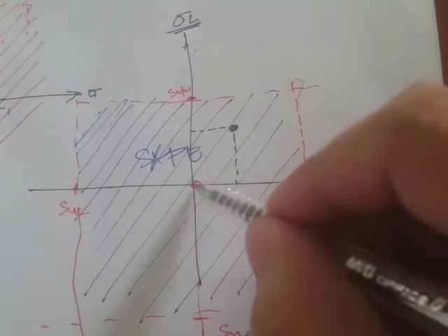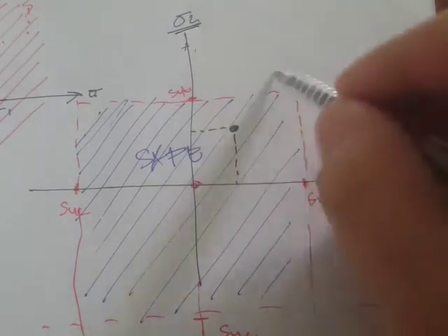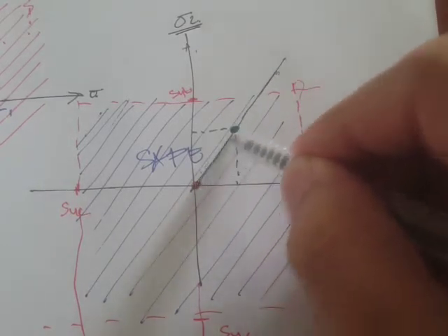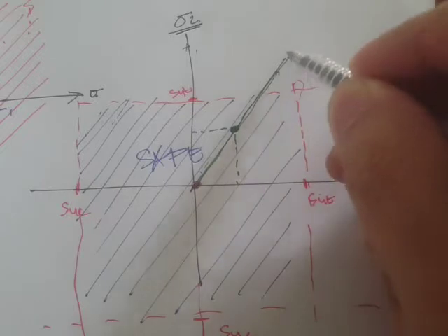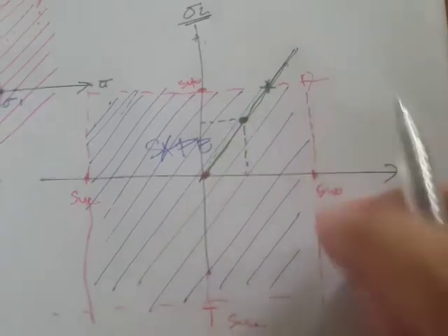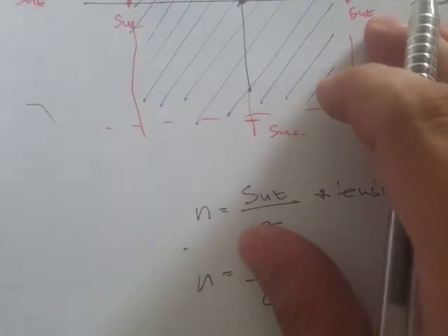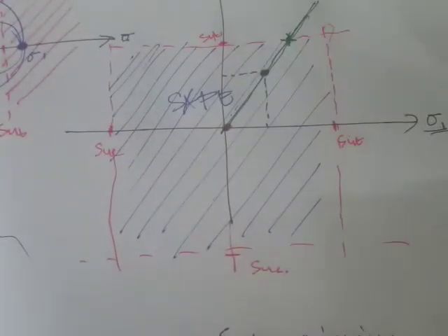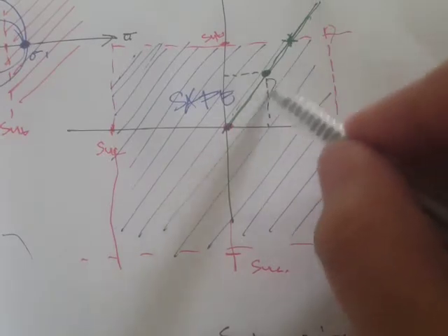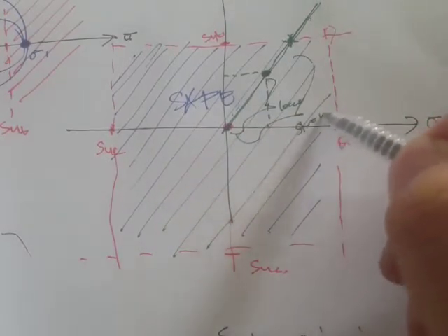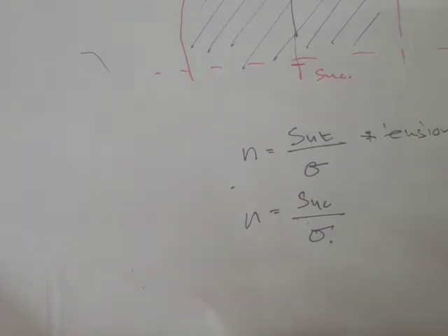And if we project a line from the origin to this load point where it crosses that, and then extend the line, then we can also make equations regarding the factor of safety about this, right? Because this is the load and this one is the strength, and the factor of safety is basically the ratio of the strength over the load.